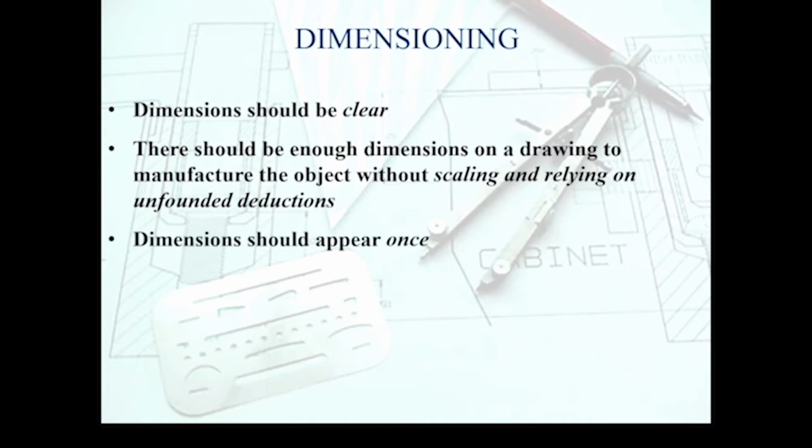We don't overdo it. A dimension should appear once, and we do not double dimension. Those are two different statements, and I'll probably have an example to show what double dimensioning really means. However, if you dimension a feature and dimension it again, you have experienced personally that SolidWorks will not like it and will throw an error, and that's correct, because there's no point creating work for yourself if it's not needed.